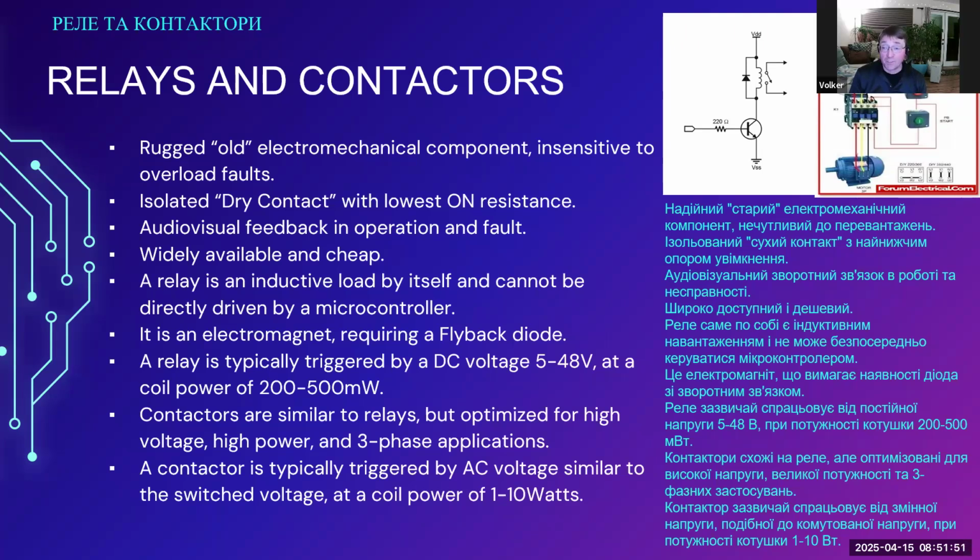You use another switching element that can be directly connected to the microcontroller, in a low side drive configuration, to switch the relay. In the image, you can also see the flyback diode that avoids the high voltage that might otherwise destroy the transistor. This diode always has to be there in some form.